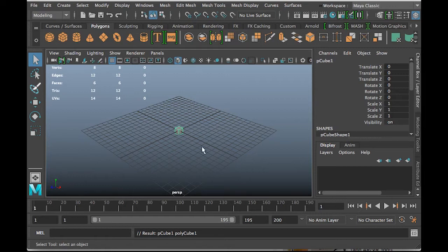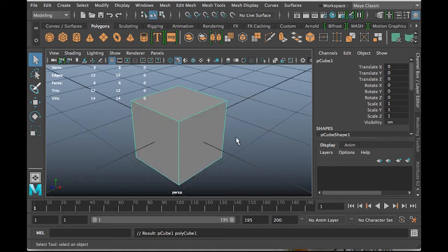About the navigation, so we created this cube. Now it's highlighted. Everybody has it highlighted. Let's press F and it zooms us into it. So remember the shortcut F. I'm going to run through a lot of things, so have a notebook and write some things down, because I will add more things than I will write later if you would like. So F just zooms to any object that is selected.